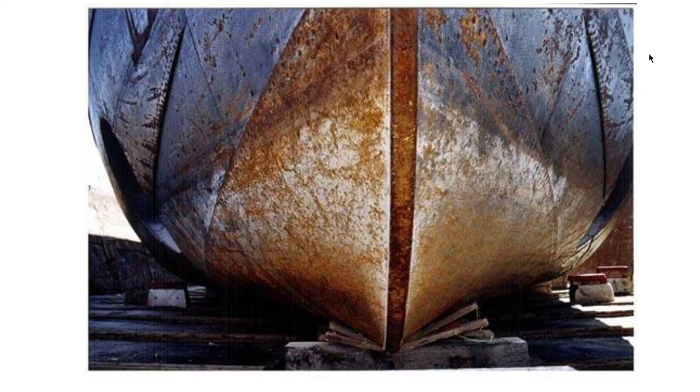So with this we come to the end of this video. Today we discussed certain things: what a keel is and what its importance and significance are. We covered what UKC, under keel clearance, is and its significance, and then the different types of keel. Before that we also saw what side shell plating and bottom shell plating are, how the numbering is done, and what a keel strake is. Then we saw the types of keel: what a bar keel is and where it is used, what Keelson plates and rider plates are, then the flat plate keel, and then what a duct keel is.